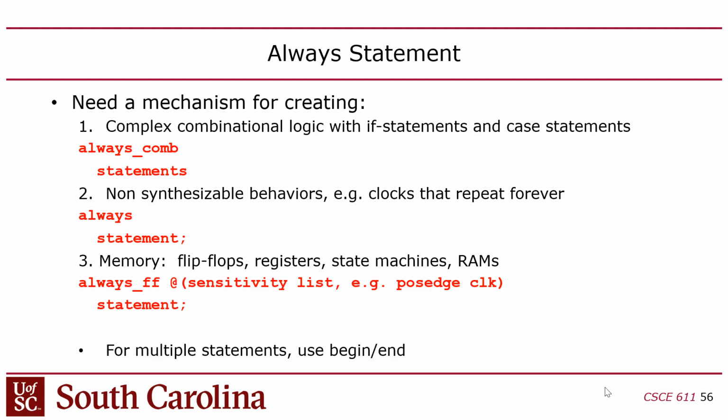The other thing you can do with always is you can use constructs like an if statement, a for loop, and a case statement. And you can call functions. There's various types of functions you can call. So it looks kind of like a more traditional programming language. And most importantly, always statements allow you to have memory. So you can actually have flip-flops. You can make a flip-flop.